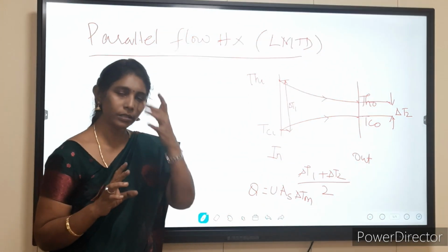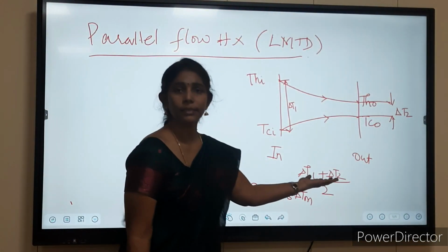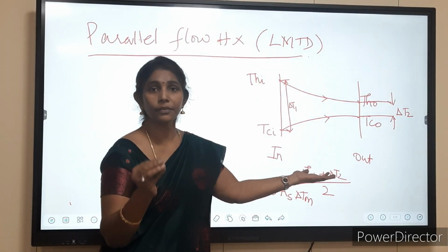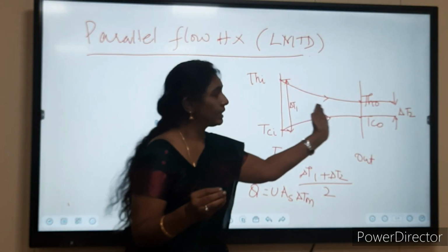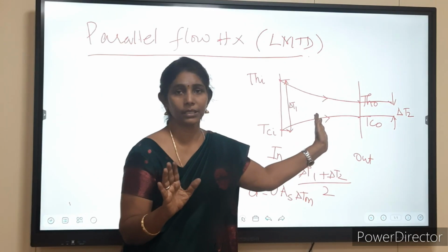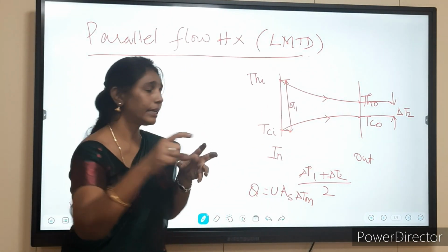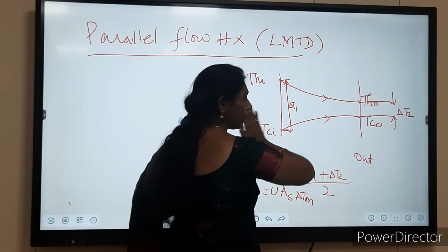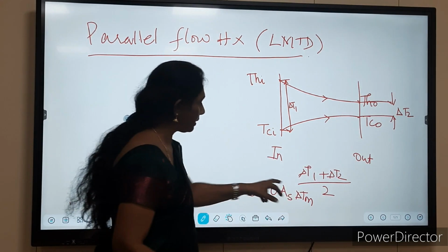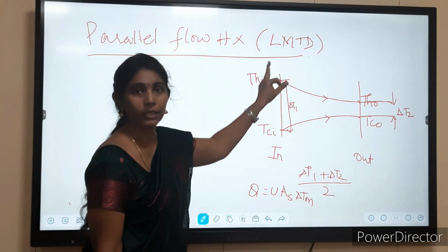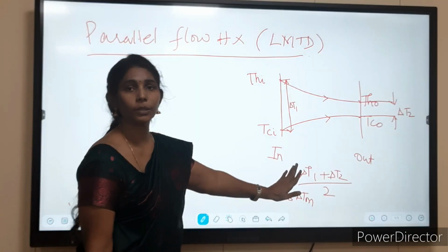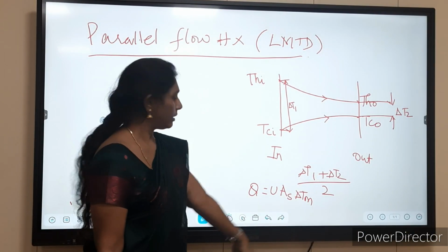No, it is definitely not okay, because this value, that is the arithmetic mean, is not going to give you an idea about this exponential degradation in temperature. In order to capture exactly what the degradation is here along the length of the pipe, it is always essential to calculate LMTD only. So that is why we are worried about the derivation of LMTD. Okay.